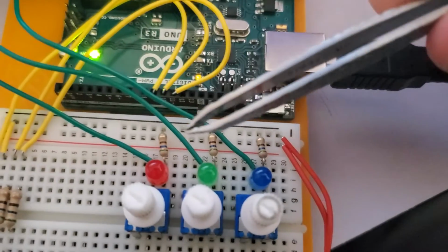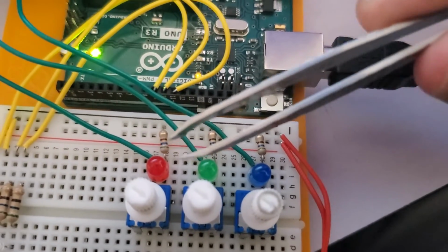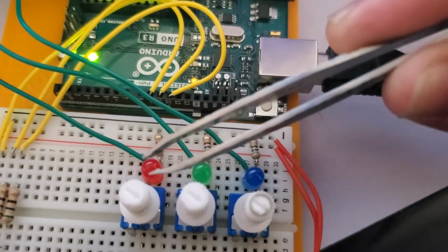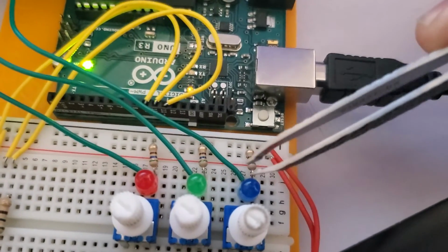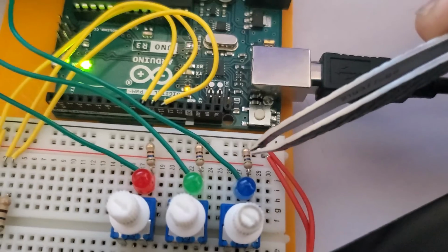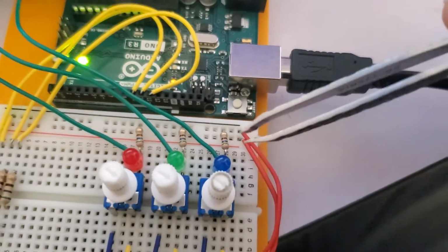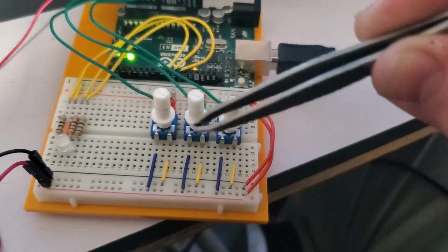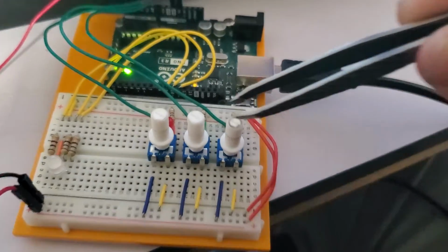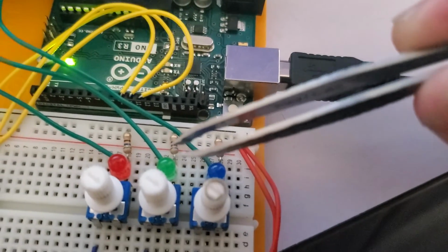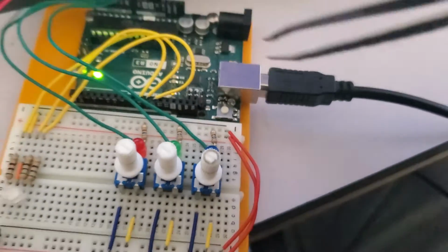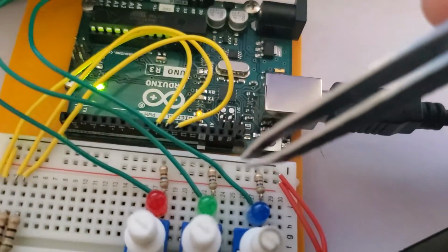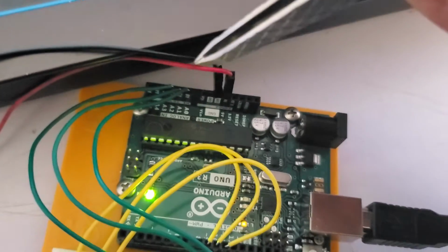To give myself a little indication of how much red, green, and blue are in each, I've just installed these little LEDs right here so we know which potentiometer is which, along with a little resistor on here. Because the power is going through the potentiometer to get to those LEDs, they will stay off until we twist the potentiometer, and then you'll see them slowly brighten up. And you can see with the potentiometers as well, the green wires are in A0, A1, and A2.